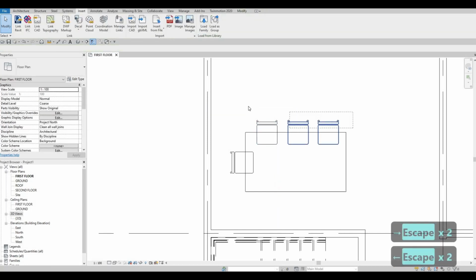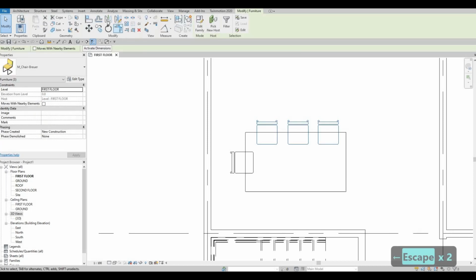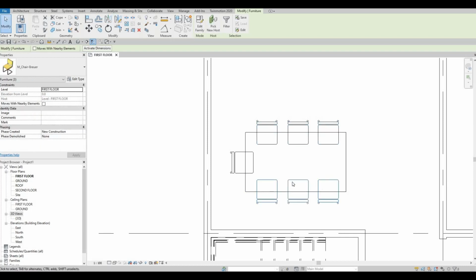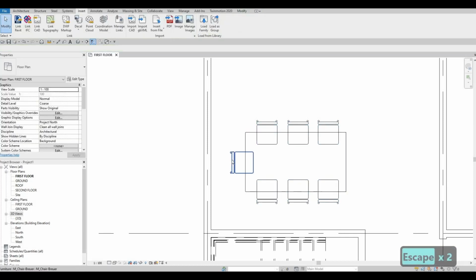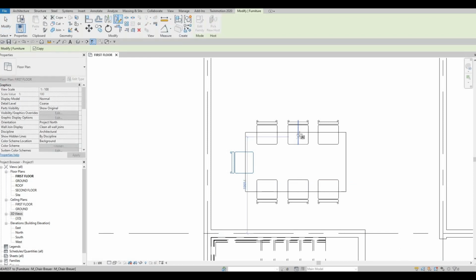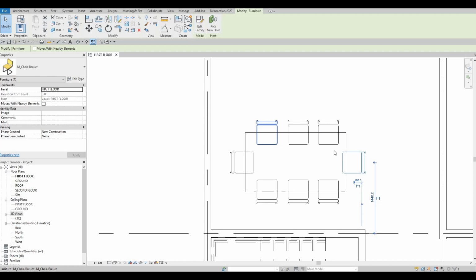Okay, so now select all of this, and then you can click on pick axis. We have the midpoint right here, and it will be created. You can also select this one, and you can select mirror draw axis. This is good as well. If you don't have the midpoint, you can create your midpoint, and you can draw it like that.